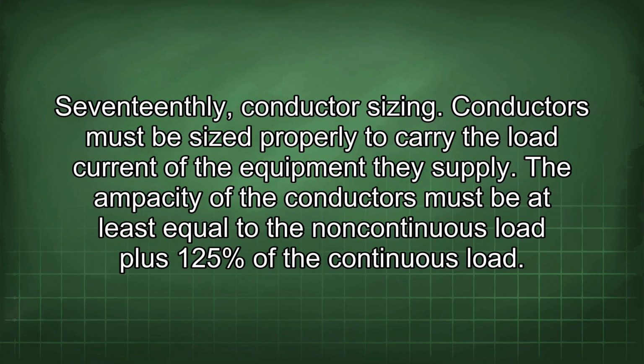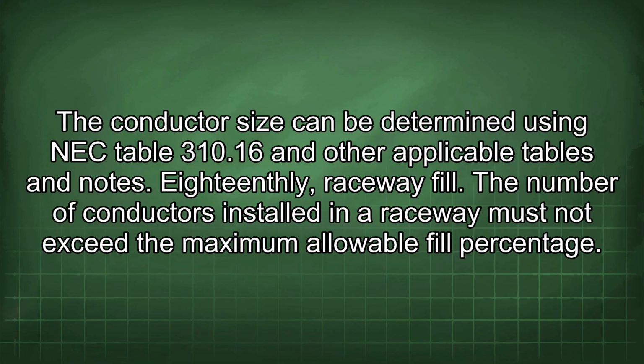17thly, conductor sizing. Conductors must be sized properly to carry the load current of the equipment they supply. The ampacity of the conductors must be at least equal to the non-continuous load plus 125% of the continuous load. The conductor size can be determined using NEC Table 310.16 and other applicable tables and notes.